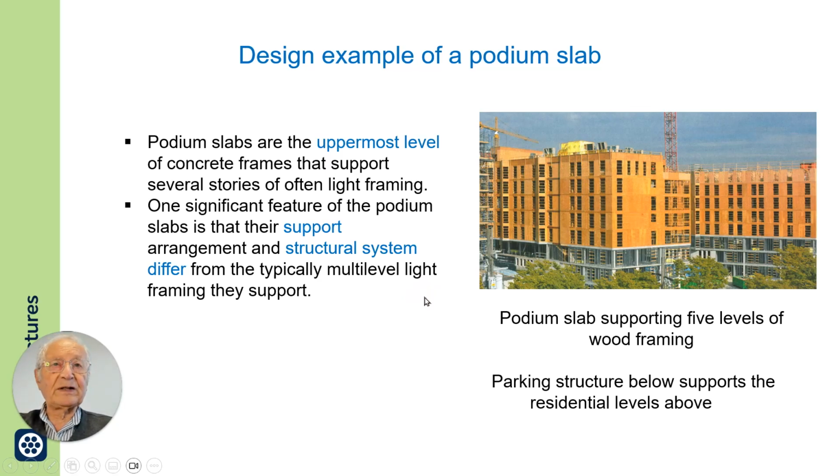One significant feature of the podium slabs is that their support arrangement and structural system differs from the typically multi-level light framing they support. Column lines, wall lines above do not generally line up with the supports below.